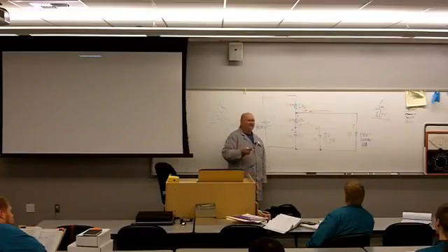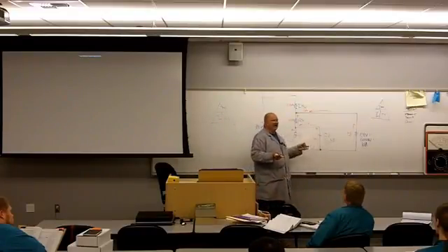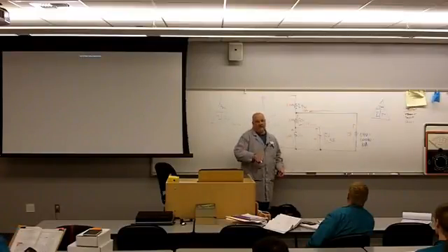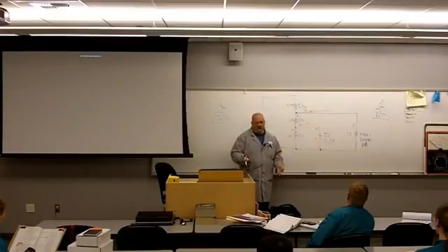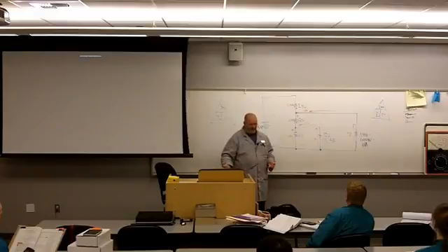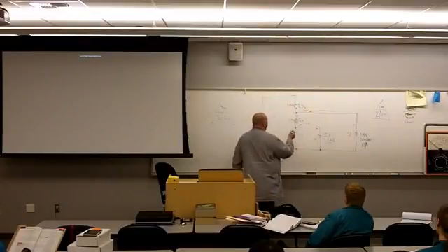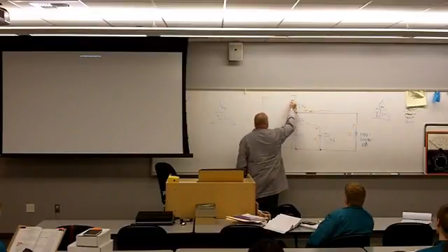And the reason that we use 1/10 is that as these loads come on and offline, the circuit's going to have stability because that CB is not always going to be on. And when we turn the CB off, we don't want the whole circuit to go cattywampus. We want it to be somewhat balanced. Same thing with the radar system. So it's a thumb rule. It's not an absolute. It's a thumb rule that should give us consistency of operation for this circuit. Make sense?